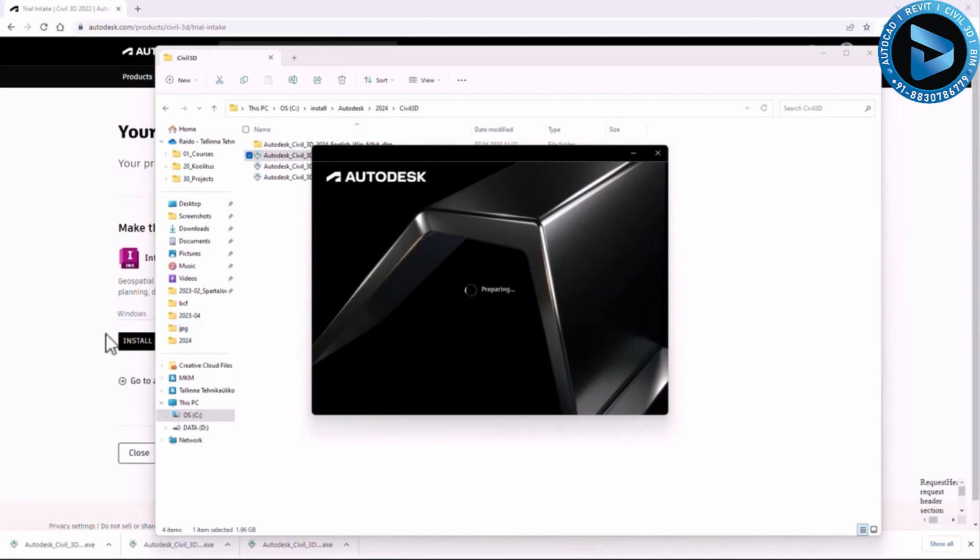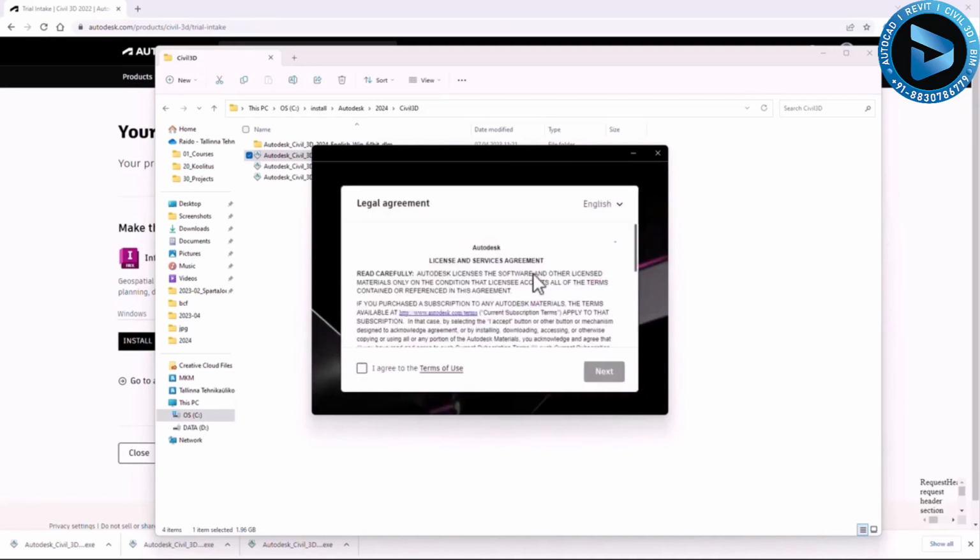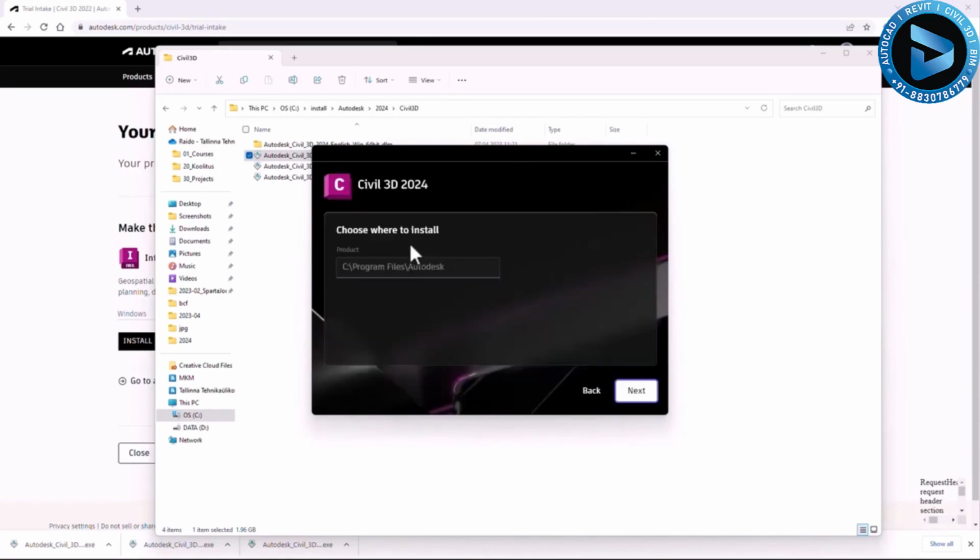If you select install directly from the website, you will get the installation screen a lot quicker, but during installation you start to download those files, and altogether maybe it takes a similar amount of time. So you have to agree with the license, hit next, and then you can select location. I usually keep the default location, and because I already have AutoCAD installed, I can't change it anymore. I hit next. I can select some additional components. Of course, I do want to have Subassembly Composer as well.